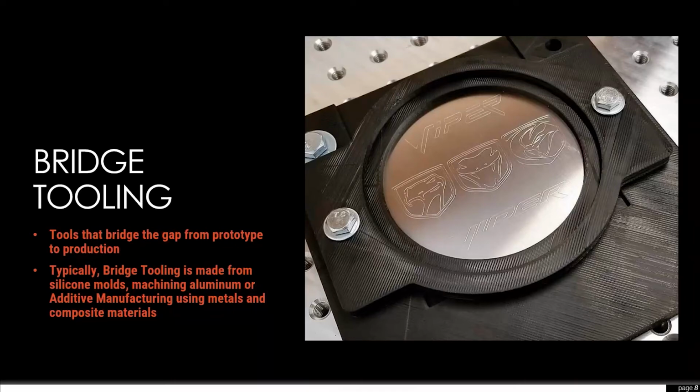Typically bridge tooling is made from aluminum machined parts, or it can also be 3D printed. This part on the right here is just a simple 3D printed fixture, but it's made for scribing or acid etching into parts for final production. This would probably be machined after, for full production, but in this case they didn't have the tools ready to be machined, so they had to be additive manufactured to make sure it would hold the part in place, and that the scribers would be able to dig into the metal to create those features without slipping. Once they proved all that out, we can move on to the next step.